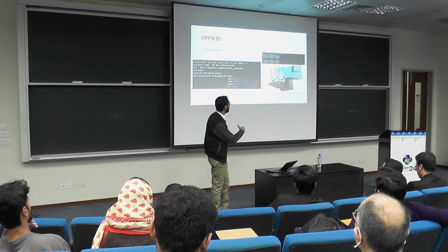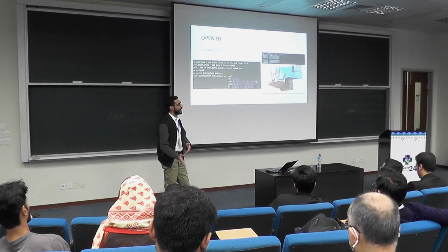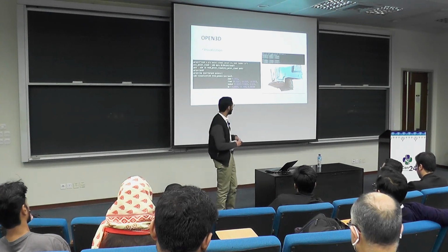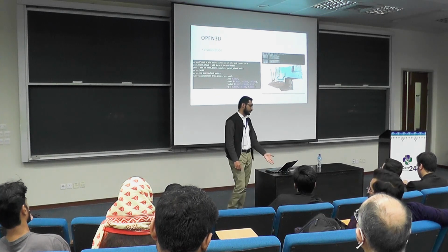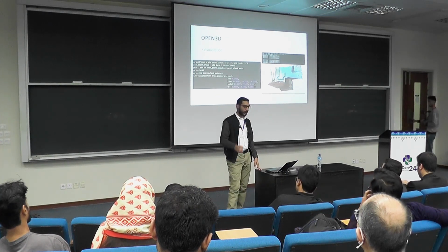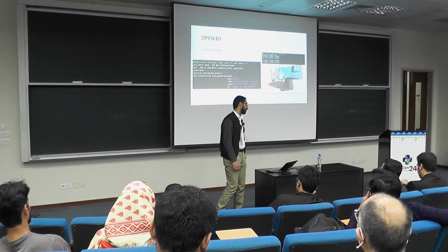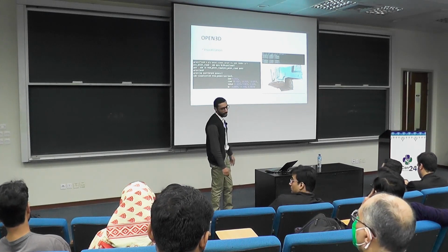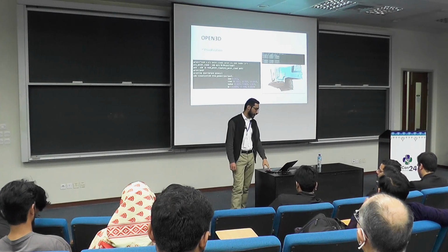In the next few slides, I've just mentioned some of the processes or functions that you can use Open3D for processing point clouds. The first one is visualization, just to visualize your point cloud after capturing it. It has simple functions like visualization.draw_geometries that you can just simply provide your point cloud, mention the zoom and all the other factors, and it will just visualize that point cloud for you.